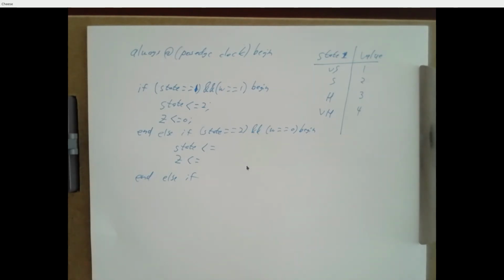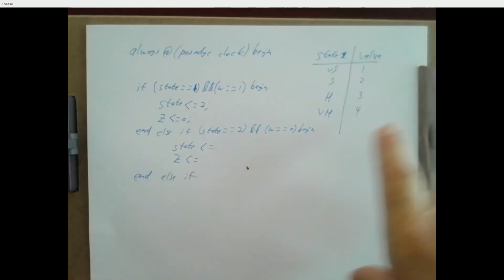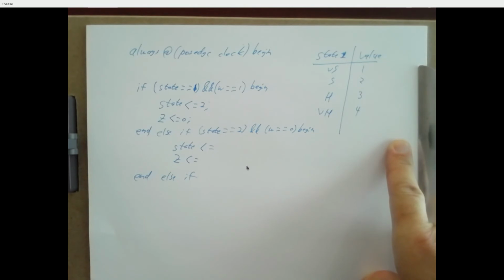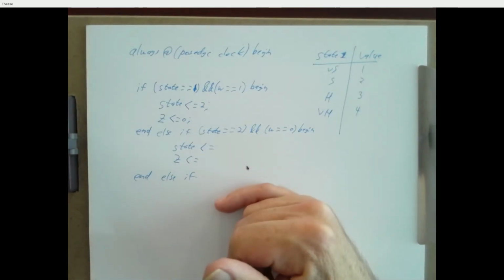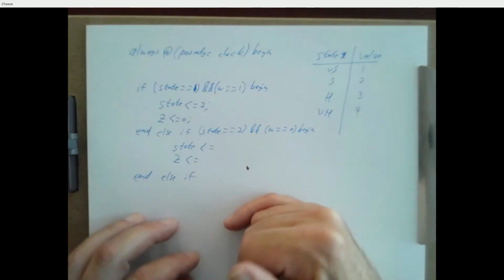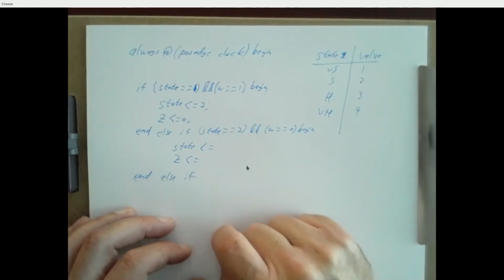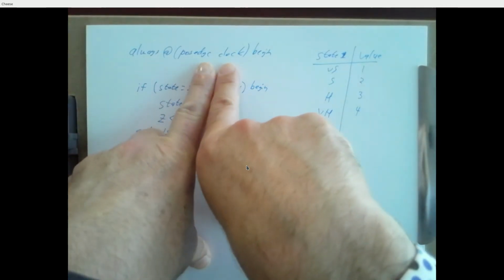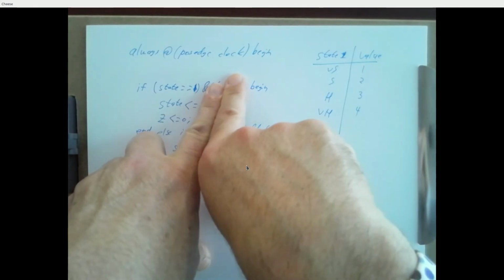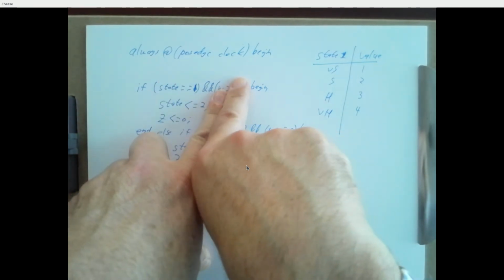And this is not exactly what an actual state machine looks like, right? Remember, a real state machine is a bunch of flip-flops and some combinational logic. So if we were to do this in that style, this code would look fairly different. We have basically a bunch of assign statements that give a value to something like next state based on the current state and the inputs. And then we have an always block which says when the clock ticks, set state equal to next state and set output equal to next outputs and so on.